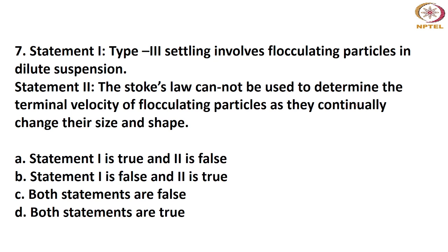again a conceptual question. Type 3 settling involves flocculating particles in a dilute suspension. The next one: Stokes' law cannot be used to determine the terminal velocity of flocculating particles as they continually change their size and shape.